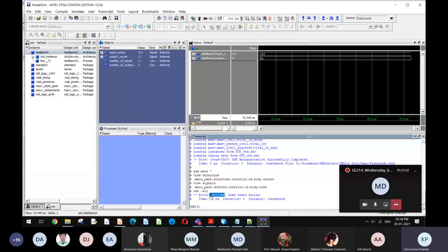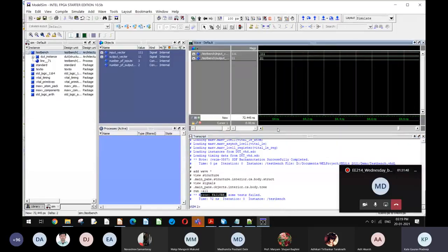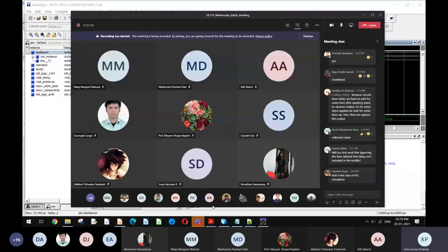Now I want to find where the error is actually. Let's say I want to debug my design. I have made some design and I see this error. So how do I find out where that error is, or for which test case such an error appears? So for that, as we discussed earlier, we can see the output file of this test bench. So I'm going to the outputs file. Again, the output file is located in the simulation directory, and inside that in the ModelSim directory.